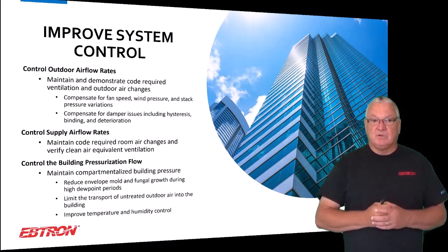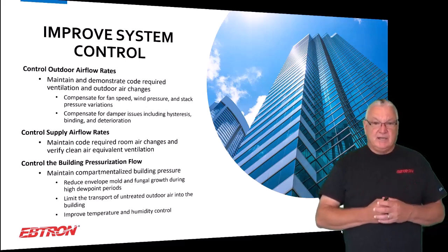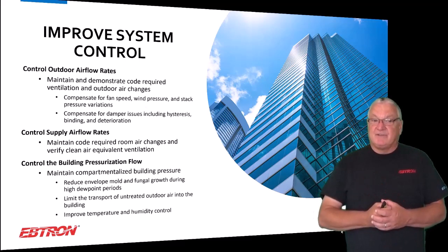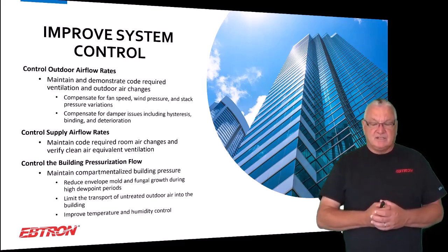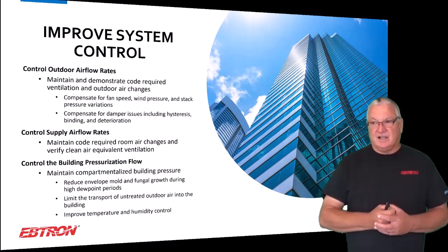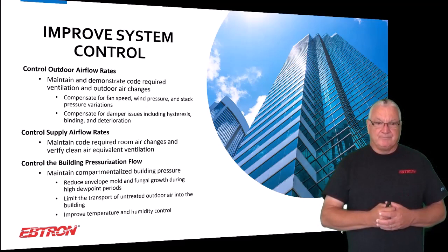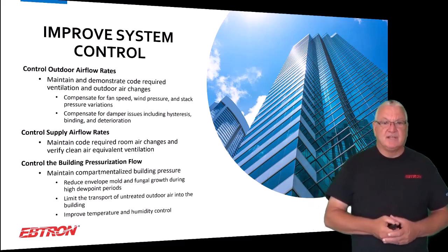The only way we're really going to pull that off is by controlling airflow rates. And depending on where you are in the country, if you're in a climate with a lot of moisture, you really have to do this, or you're going to have mold and fungal growth problems. But it's not just that. Even in dry climates, you're bringing in untreated outdoor air before it ever crosses a filter. So there's things that you have to think about here.